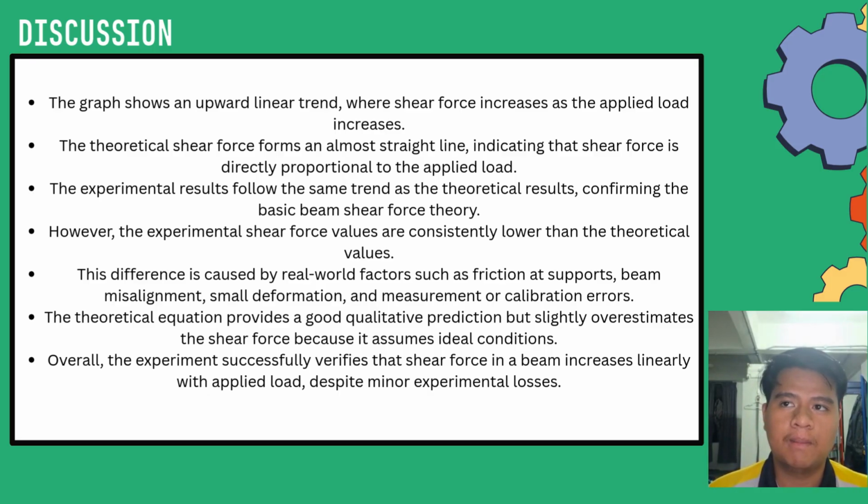Firstly, based on the graph, we can see an upward trend as the applied load increases. Both the experimental and theoretical shear force also increase. The theoretical graph forms an almost straight line, which shows that the shear force is directly proportional to the applied load. This means that when a larger load is applied to the beam, the shear force inside the beam increases proportionally. This result is consistent with basic beam theory.